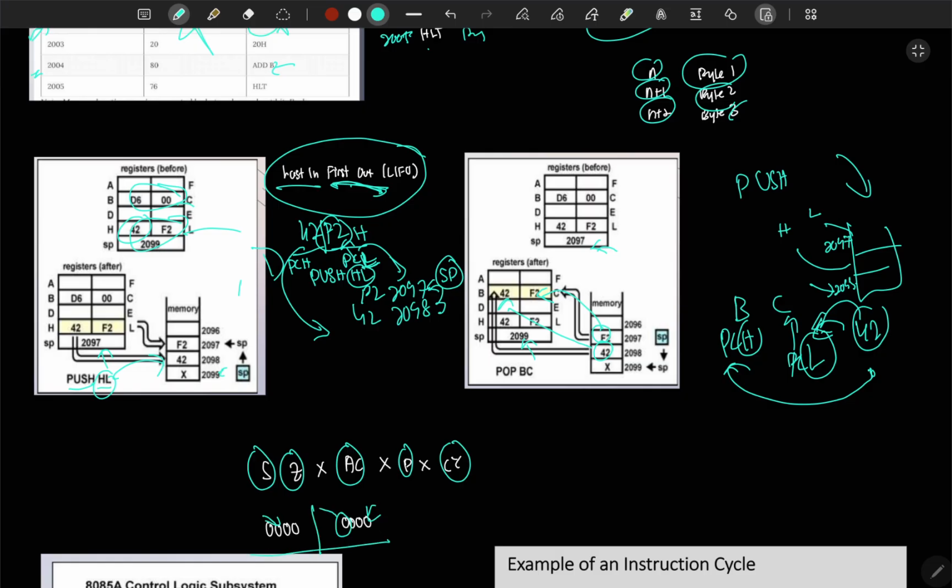So if from this to here we have carry, maybe we have 0 0 0 0 1 0 0 0 in register A. In register B we have as such. So these two gives this, so there is a carry, then our auxiliary flag will be 1. Okay, and then we have our carry, this bit has a carry, so this is 1. And zero means if all the data is 0, this means 1.